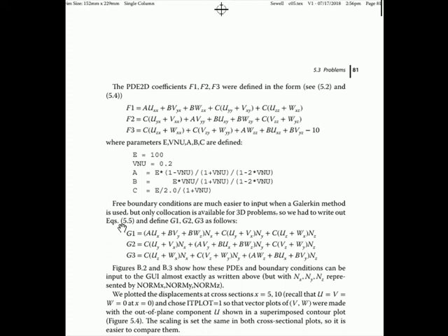So in the 3 boundary segments where the forces are given and are 0, we're just going to have this. This is just sigma xx times nx plus sigma xy times ny plus sigma xz times nz. And we'll just have to write all that out. We'll have already defined A, B, and C. But that's going to be a mess to input on 3 different boundaries, so I'm going to cheat again and read it from a file just to save some time. Okay, here we go.